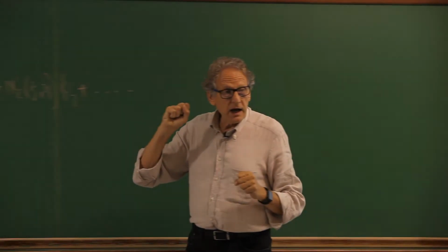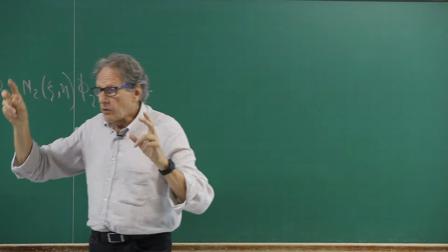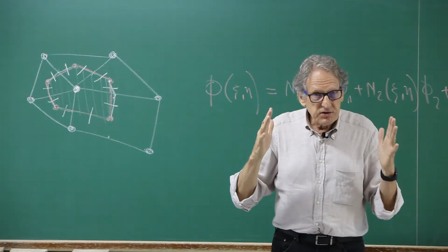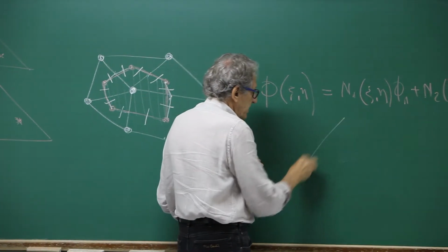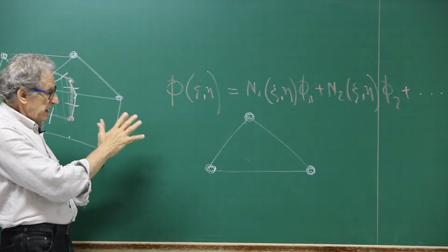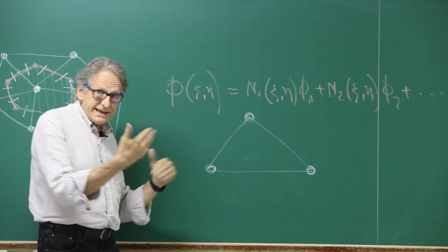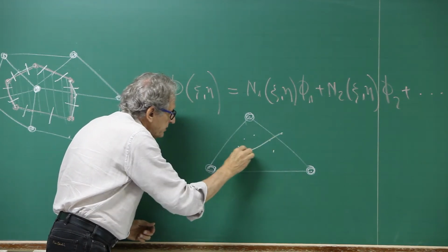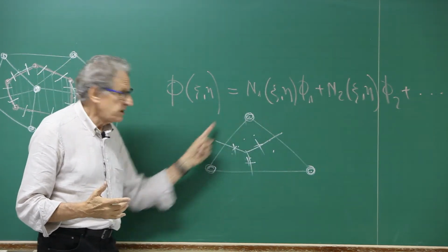See, there is no need for any kind of gradient reconstruction, Green-Gauss theorem, and surrounding nodes, because it's clear that if I have, let's say, a triangle, I can have some phi which is a function of x and y and xi and eta, and if I am inside here and my integration points are here inside, I can find the gradient easily just using those 3 points.